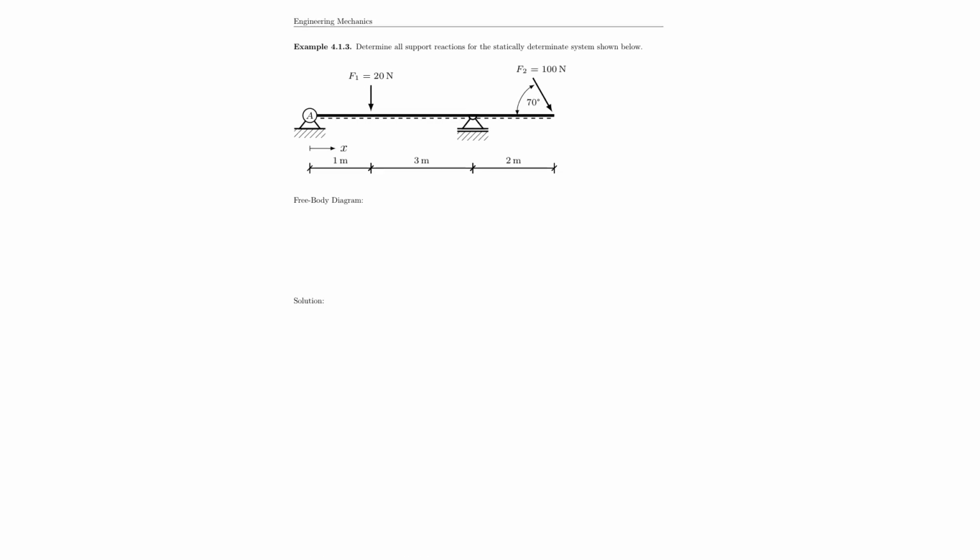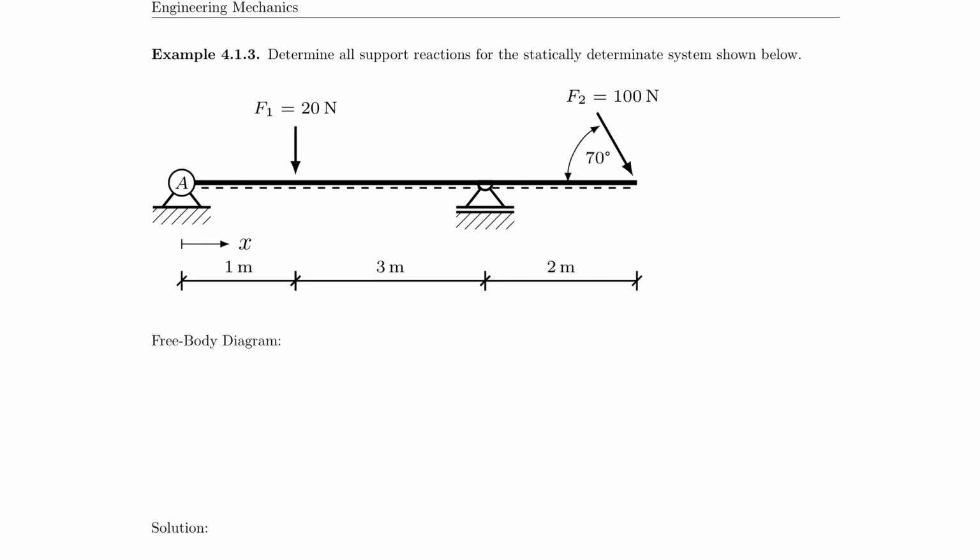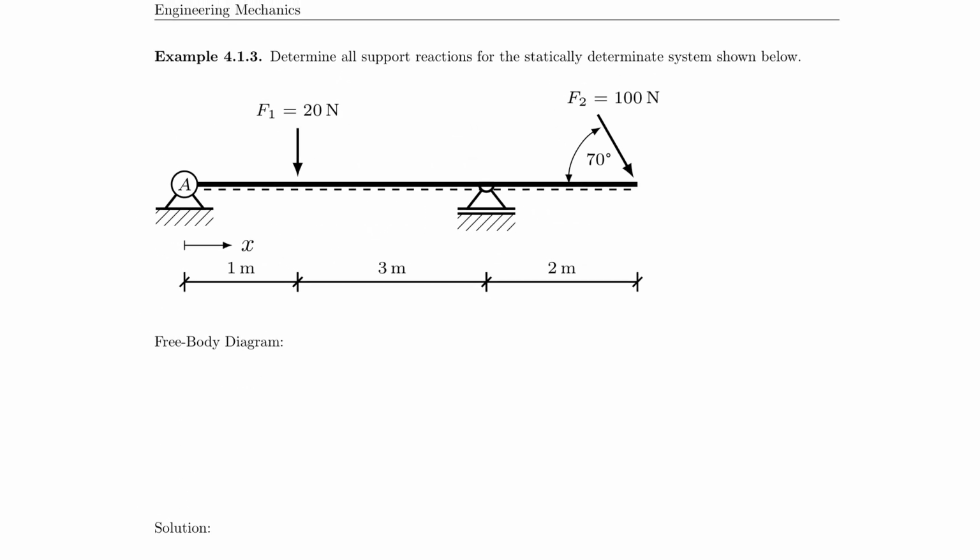So here we have our next fun example, which usually causes confusion in the classroom simply for the fact that we now have a support reaction that sits in the middle under the beam. And please notice this half circle. It's not a full circle that would actually turn this into a hinge, and therefore this part of the system would be unstable if there was a hinge here.